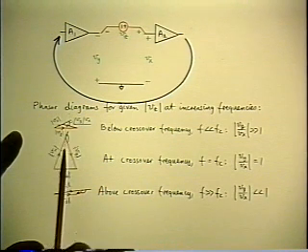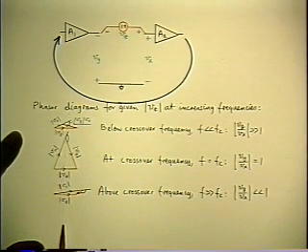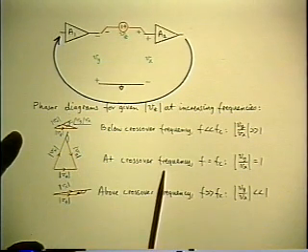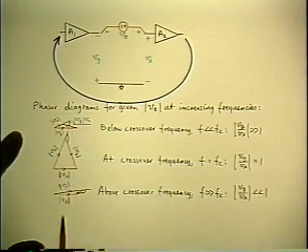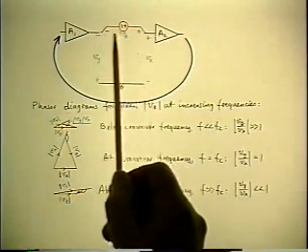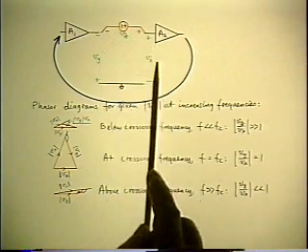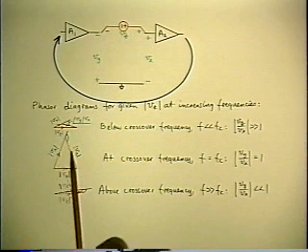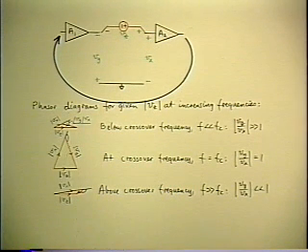So you can visualize an evolution of the triangle as you increase frequency. And you can see that followed through on the oscilloscope if you increase frequency at constant amplitude Vz and you observe Vx and Vy on a scope. You can see the magnitudes and the relative phases going through this evolution.